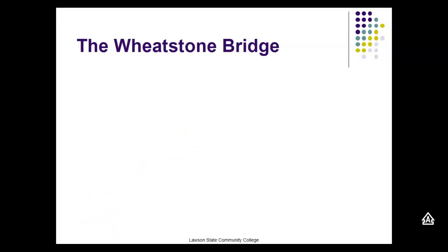So what I would do, guys, is take a fixed resistor that I know the size of. Right now I've got a 10K. What's the color code for a 10K? And then I've got my thermistor. Normally we put sensors inside a circle, and then we would put a T in here. And sometimes they put the little degree symbol. Now, right now, what we'll do is take our output right here across the thermistor.